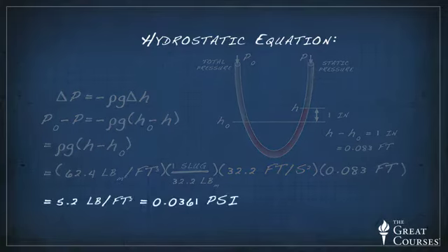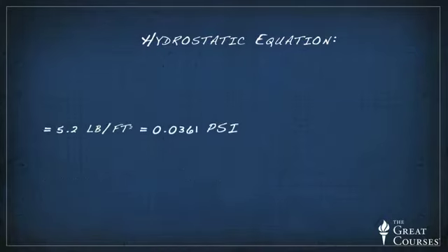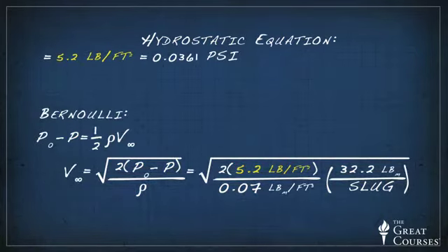These values give a dynamic pressure of 0.036 psi. Now, taking my value of density and solving for velocity out of the definition of dynamic pressure, we see that the test section velocity is 69 feet per second. So making only one measurement of dynamic pressure in the wind tunnel, coupled with measurement of the ambient pressure and temperature in the room to find density, I can easily find the test section velocity.